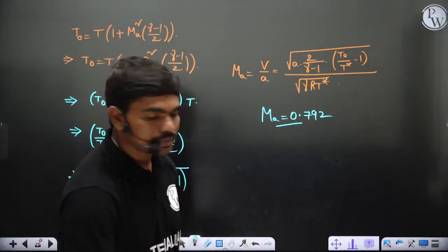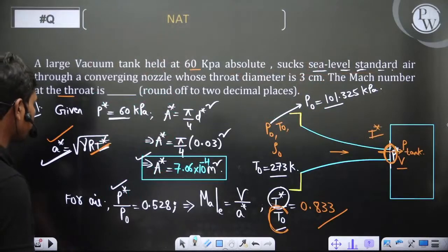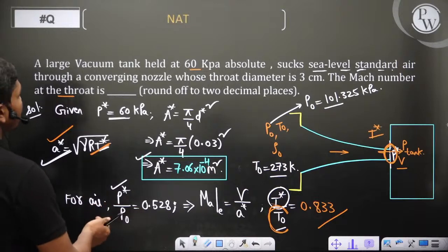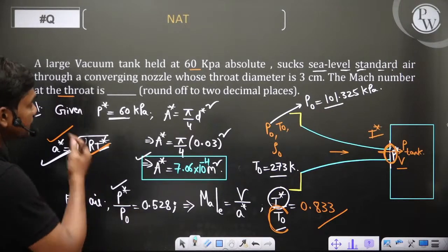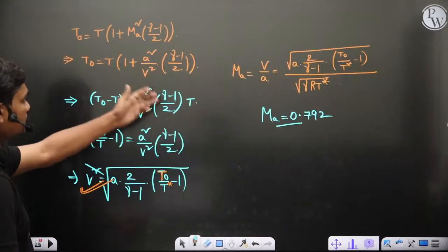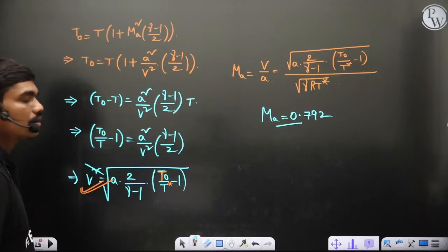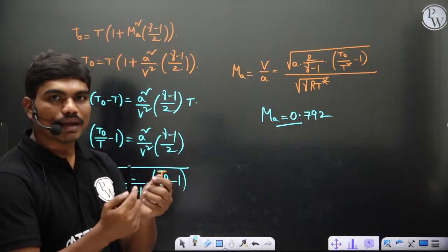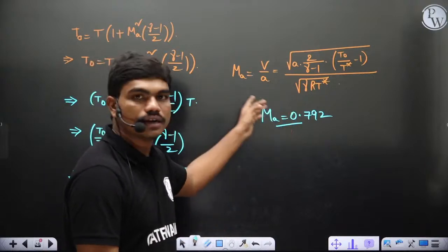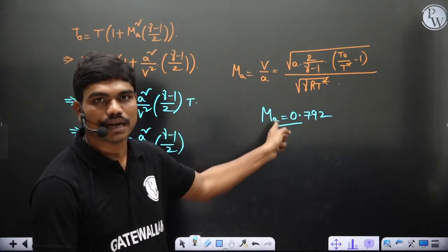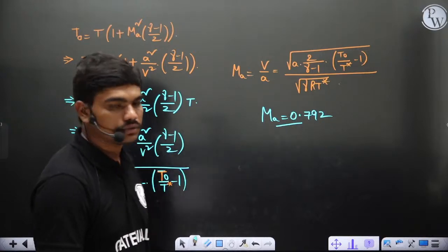So we were given stagnation pressure. Achha, stagnation pressure is given, then you can calculate Mach number directly. Yes, you can calculate the Mach number also, but to calculate this Mach number we need these things. Basically, to calculate the Mach number somewhere in the flow, you can use this P naught. So P naught by P star is equal to 1 plus gamma minus 1 by 2 Mach square. All these things you can use.